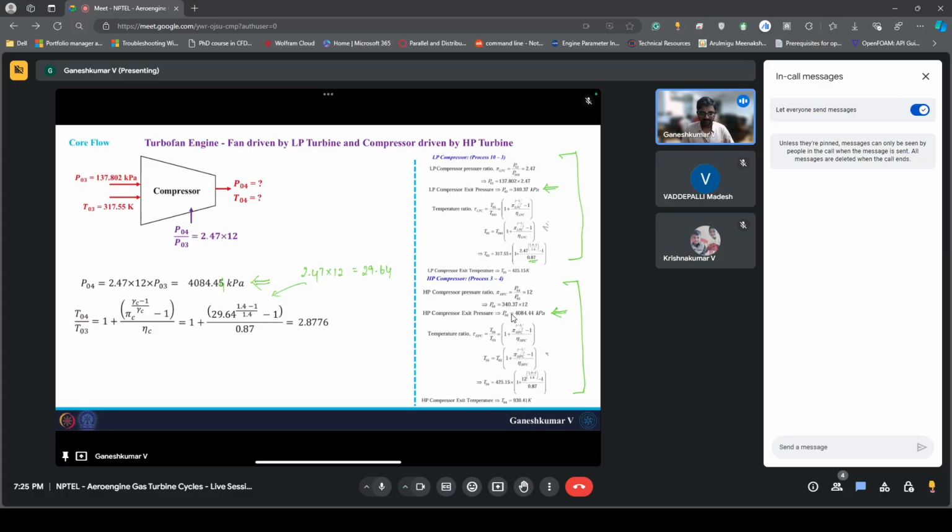Okay, so let's see what is the exact exit temperature of this compressor stages. So that would be something like 913.78 Kelvin. Okay, so there is something you can note here. The temperature at the exit of this whole compressor stage is 913.78 Kelvin, while the temperature at the exit when you divide it as a two compressor is 930.41 Kelvin.